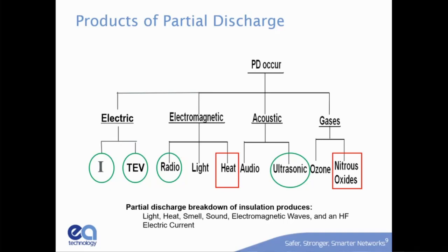It does create light. And say you were looking at surface discharge on an overhead insulator in a 500 kV substation, you could use something called a corona camera. And a corona camera is basically a UV light camera combined with a visible light camera. And so it's showing you that UV emissions from it. That's good, but you got to have line of sight to it.